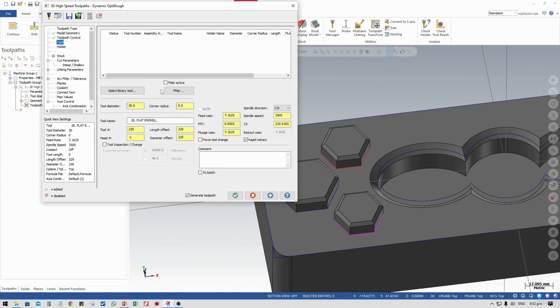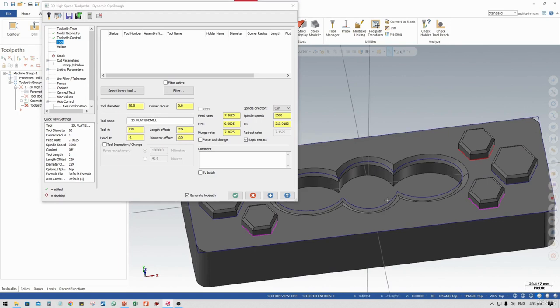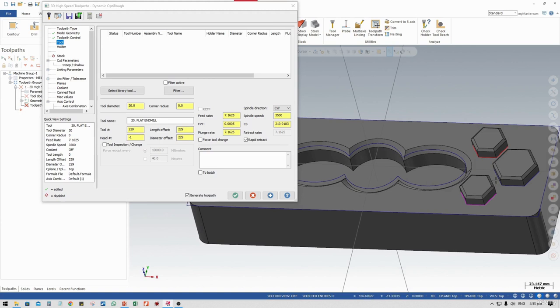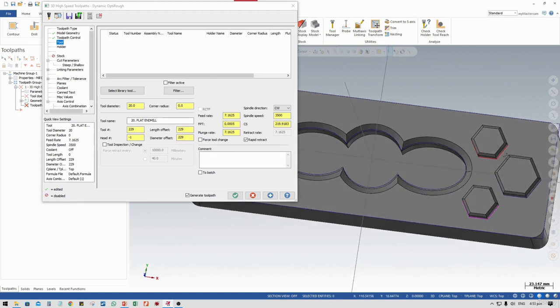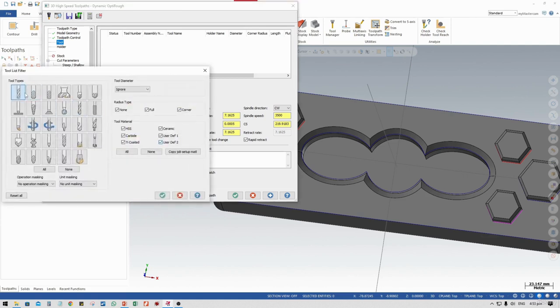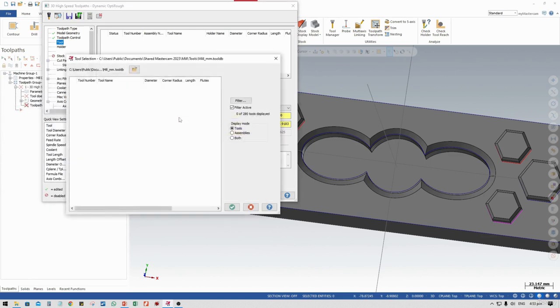Now let's move towards the tool. So you have to select an appropriate tool. You have to know how much distance we have here to create all these areas to be machined. If the distance is not enough, the cutter will not pass through this less width area and will not machine that area. So therefore you have to select an appropriate cutter. So let me define that I'm going to use an end mill cutter for the rough operation, because for roughing operation most of the time we use the end mill cutter.